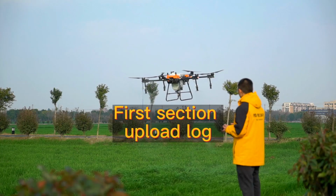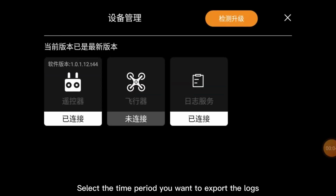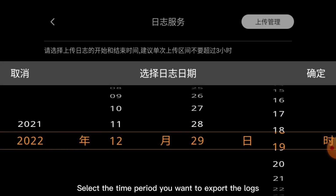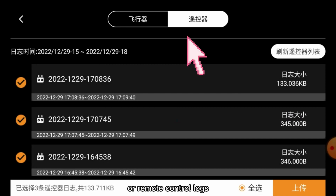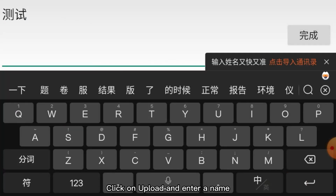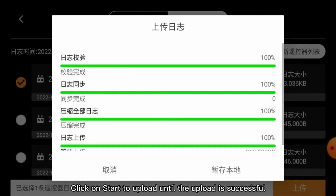First section, upload log. Open the remote control in this interface and select Device Management. In the pop-up interface, select the time period you want to export the logs. Here you can choose to export the logs of the aircraft or remote control logs. Check the desired section, click on Upload and enter a name. Click on Start to upload until the upload is successful.